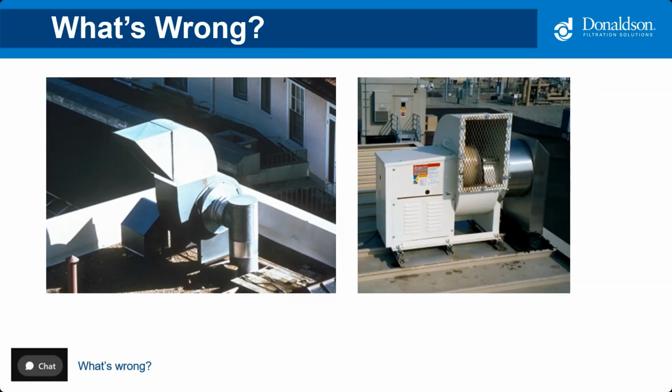Another thing I'm noticing here is what I call breaking the back of the airflow as it's discharged. The air is kind of following the housing, rotating in a clockwise direction from this angle. And then we're bending it back the other way for no reason that I can decipher. It just creates another loss in the system and wastes power and energy.